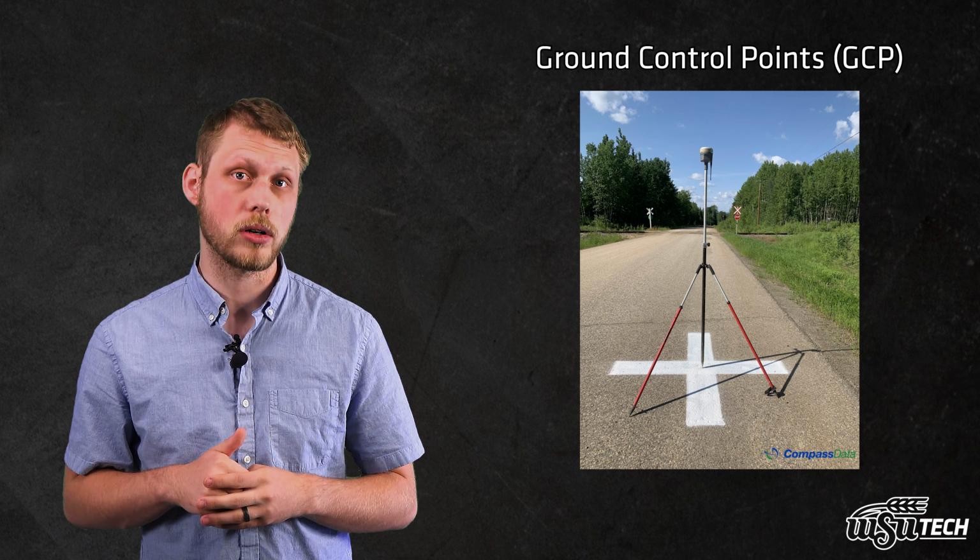GCPs are physical markers placed on the ground with known GPS coordinates. They anchor your model to real-world locations. Without GCPs, your model may look good, but your measurements won't hold up. Even just 4 to 6 well-placed GCPs can dramatically improve model precision.